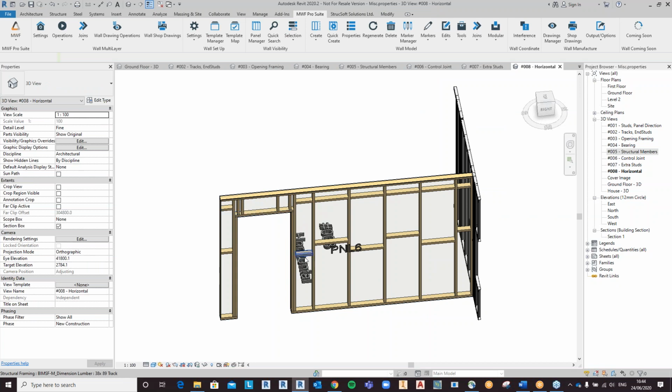And now I have my two definitions of horizontals within my panel. So I have a 100 mm stagger here, and above here I also have my horizontals applied at the top of my panel, going from N1 to N2, but just taking a break here between my opening. You're not forced to, of course, have your horizontals start from N1 and stop at N2.